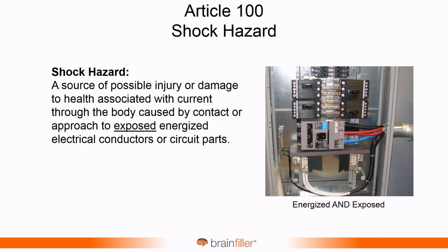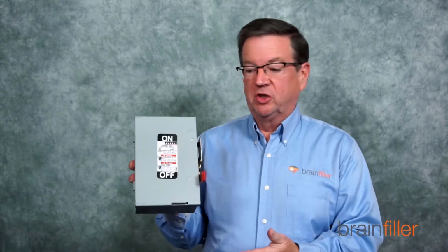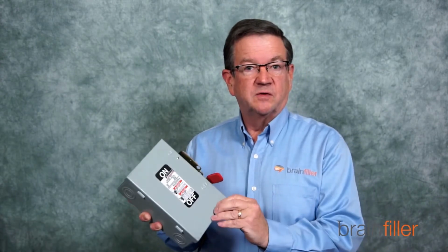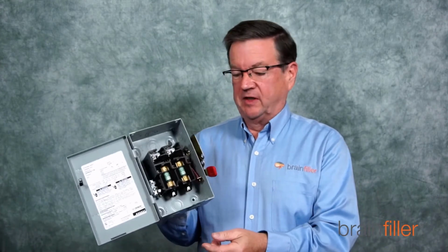Another change to a definition, the shock hazard. Now this seems simple enough. It's a source for possible injury and damage to health, but the word exposed was added because it did say caused by contact or approach to energized electrical conductors. And so there's a clarification: exposed energized conductors. For example, if you have a switch, there are energized conductors in here, but they're not exposed. So it's not a shock hazard. Whereas if you open it up, you may be thinking, Jim, the switch is off.